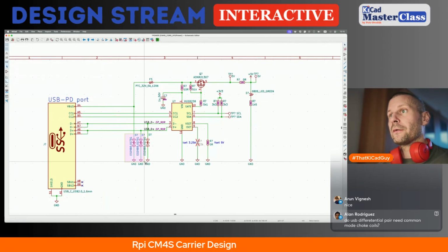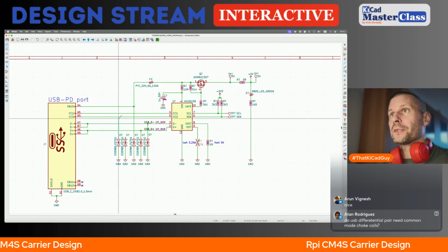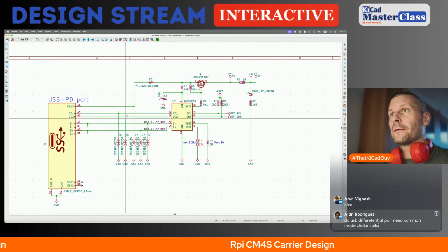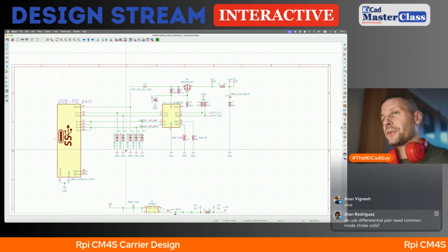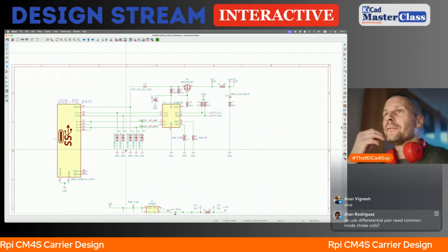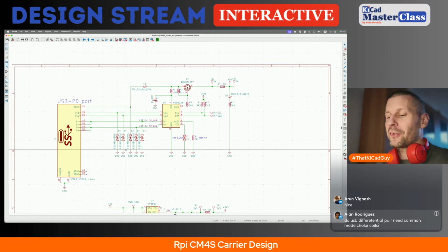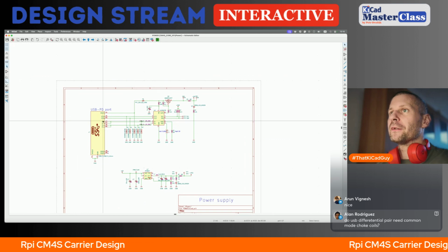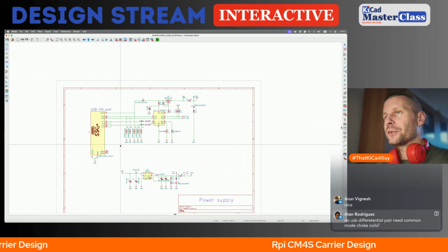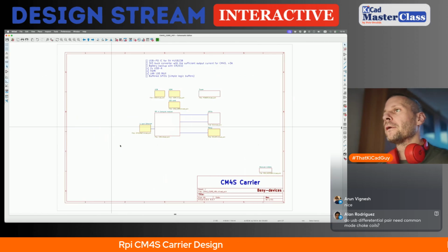And we really don't want to risk the health of the CC1, CC2 signals, which is crucially important for the power delivery thing, because through them the controller sets the output voltage on the port.